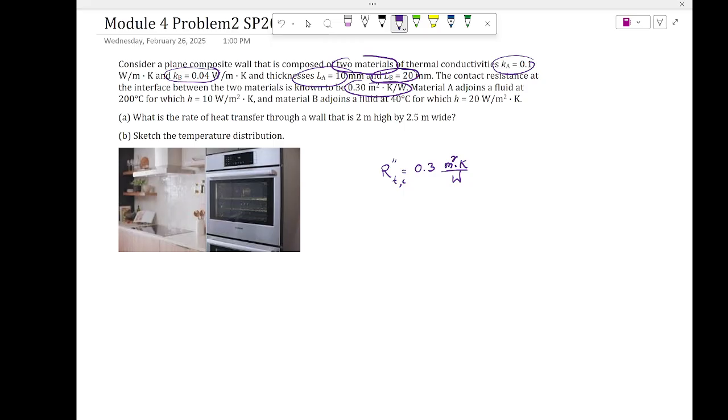So this could be one unique situation, and you would be given the contact resistance value. But here's the catch. You see, I am now showing these two plates, which have some dimensions, like the area I'm talking about. It may only be applicable if I give you the contact resistance for this particular place. It may only be applicable for this particular scenario, right? But it is not universal. To use it in a universal way, you may want to use the contact resistance per unit area.